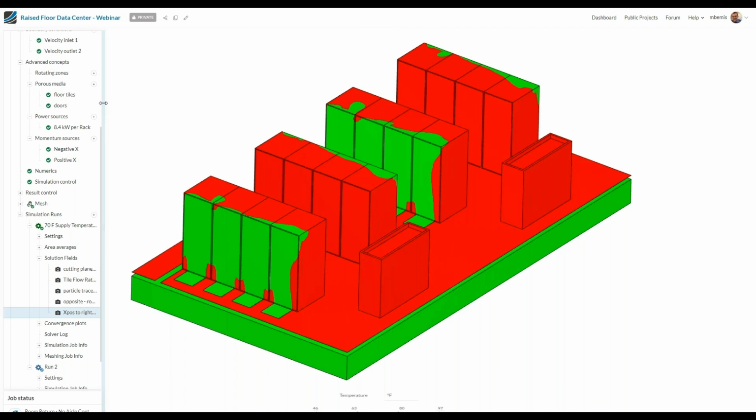So earlier I mentioned that ASHRAE standard. Essentially, it says airflow needs to be between 64 degrees and 80 degrees Fahrenheit at rack inlet. Now, SimScale allows you to modify your legend and the min and max number of levels, and I dialed this into sort of a yes or no. I guess it's too cold, good, and too hot. So we got three options here.